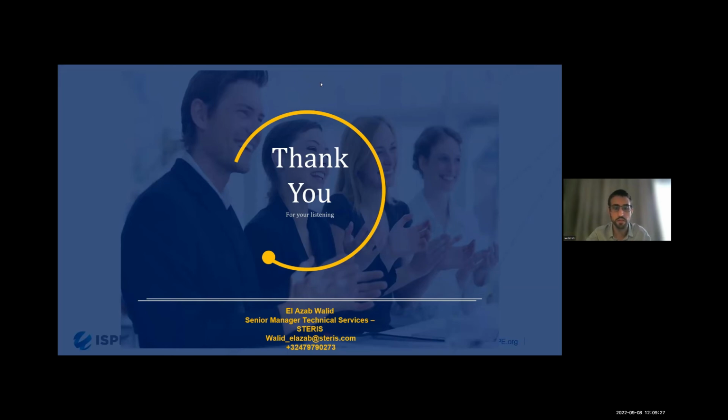I understand a new company may not know all that at the beginning, but for those who know, you want to know what is your process, map the process, assess the risk, and based on your CCS, where are the measures that you need to have, what are the controls, and where you will put in your sampling points. If you need to clean the isolator, for example, do you need spray balls, etc.? All that needs to be even in the basic design, and then you complete it during your design phase, IQ, OQ, PQ, etc. And you complete it and then confirm if it is still the same level, or if you need to add other measures and controls. So from the beginning.